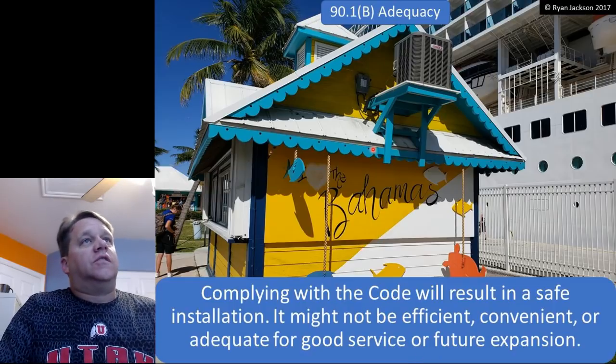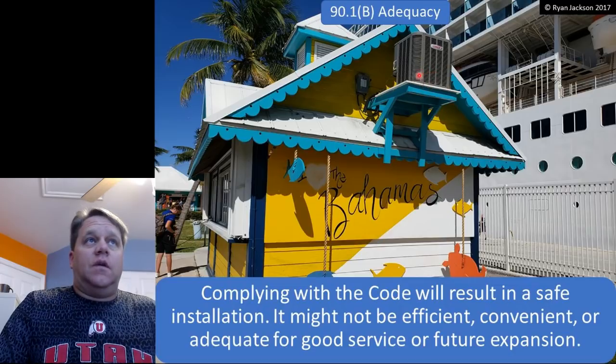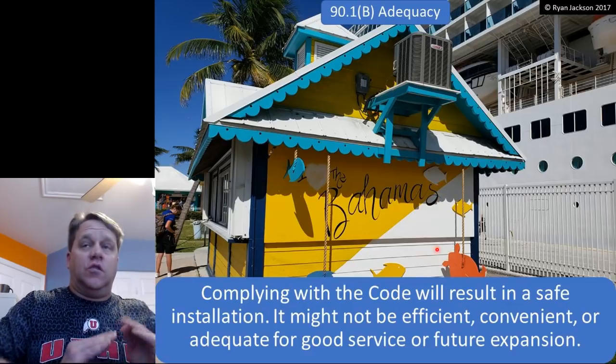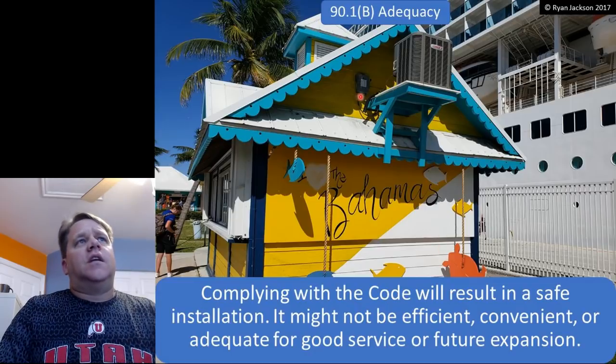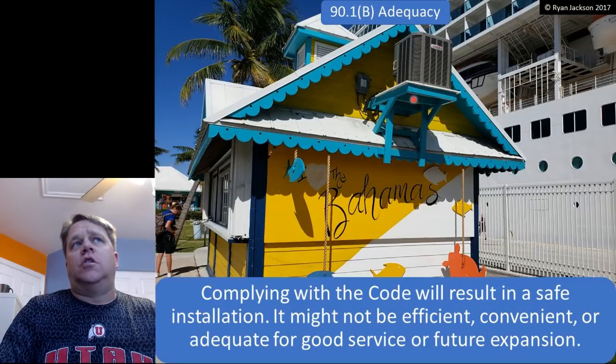Take a look at this picture I took a couple months ago. We've got the air conditioner up here, and we've got its disconnect up there. Is that safe as it relates to the use of electricity? Sure, absolutely. That disconnect is providing fuse protection for the conductors that are supplying it. If I ever need to work on the air conditioner, I can shut it off.